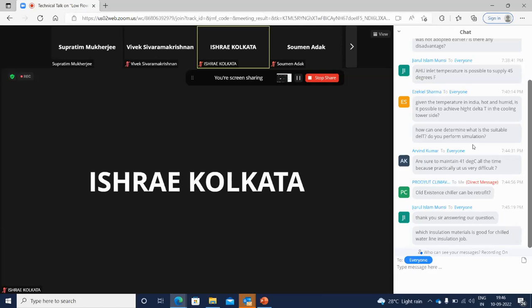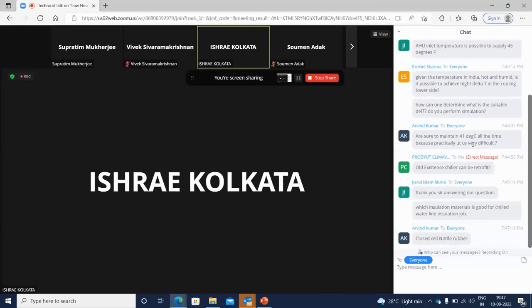Which insulation material is good for chilled water line insulation? I think the other members in the society are more knowledgeable than me to answer your question regarding insulation. But I think closed cell nitrile rubbers are good at the moment. Obviously we have done away with thermocol sections and all. We have stopped using it, or we have reduced usage of that. Closed cell nitrile rubbers are good. I think people are also using PIR insulation in some cases, which is also giving good performance. But anyway, I'm not an expert on insulation, so I'm nobody to answer that.